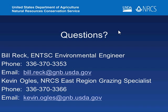And the spring development standard has a lot of discussion. It does talk about wetland impact in the standard. And yes, you can't impact wetlands, but you can put in a spring and not impact wetlands. It has to do with the depth of the water table, the depth that you're putting in water, and the land use type where you're putting it in. If you're putting it in a pasture area that's prior converted, that's not going to be an issue.